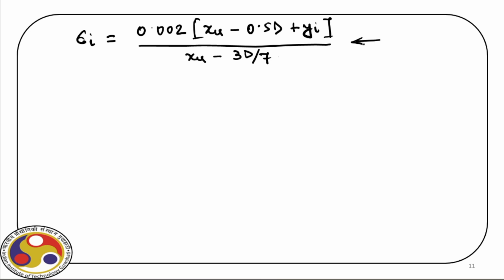It comes from the strain profile in the strain diagram. I leave this as an exercise for you. So this is a home task. You just verify this. The moment we identify this strain, we can quantify the stress in the steel because now we know at the ith layer the amount of strain. So if we refer to the stress strain diagram, we can quantify this.